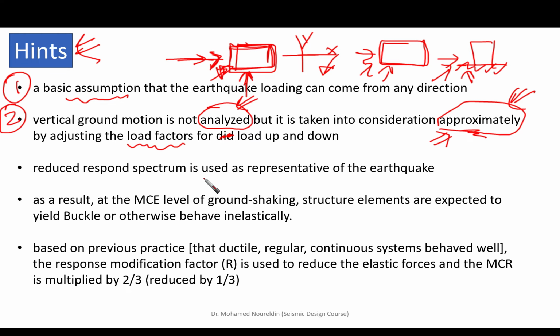A reduced response spectrum is used as representative of the earthquake. Do you remember when we said that we have a response spectrum and a smooth response spectrum? We are going to use this, but we are going to reduce it, as we will see, to get what we call the inelastic response spectrum. What is the reason for this?